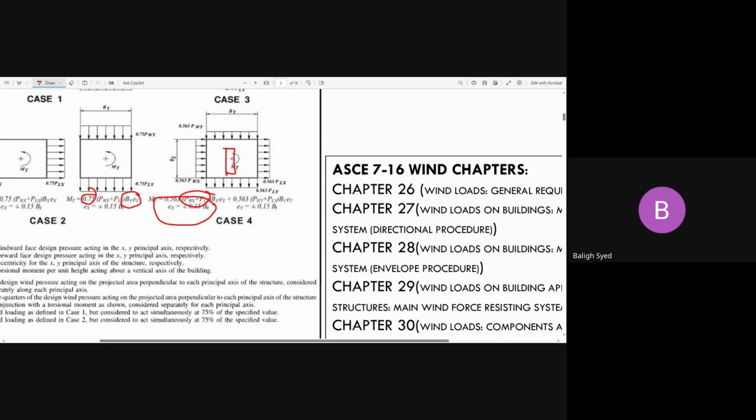Someone can come and argue with us for, let's say, a four-story CFS building. Some of you have been doing CFS buildings. Yes, someone can come and argue with us, okay, why are you not considering the torsion load? But there is another reason, because we designed for 2-hour fire rated shear walls, and the concept is, okay, one breaks down, the diaphragm is disconnected, and the rest of the structure will stay. So that's why we have the shear walls in every single unit, right? You are understanding what I'm trying to say. So in that case, that's why I never apply these loads over there.